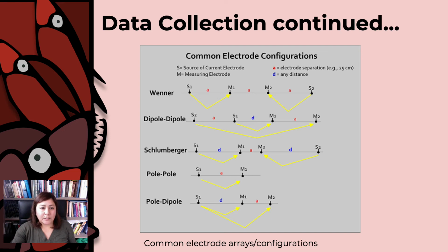We estimate that it takes approximately 2 hours to survey a 20 meter by 20 meter or 400 square meter area at this resolution. This process can be sped up by connecting more probes to the mobile frame, though the resulting instrument is often clumsy to use and only works in ideal field conditions.